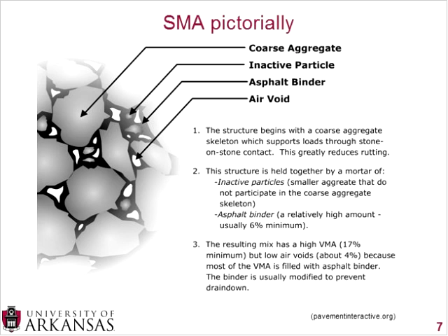We'll go into more details on the mix design in further slides. The resulting mix has a relatively high VMA, about 17%, but it does have lower air voids, 4% or even less, because most of the VMA is filled with the asphalt binder.